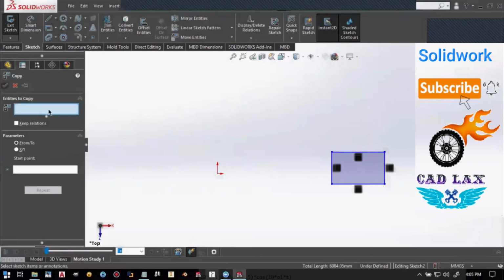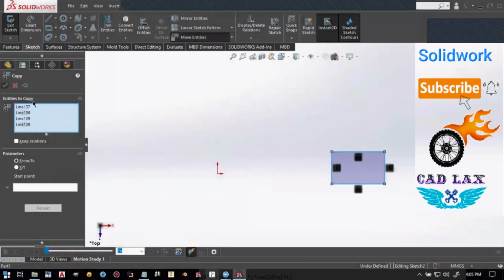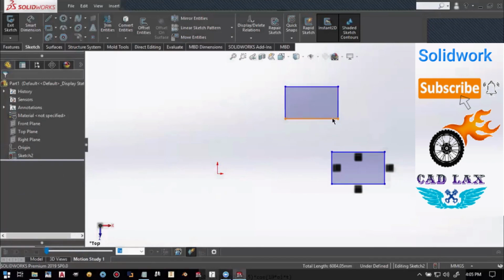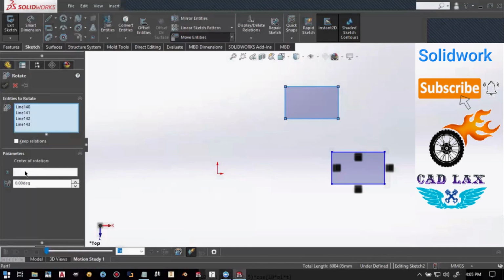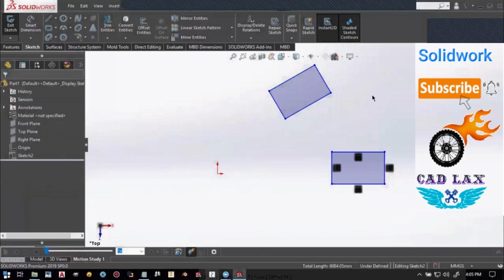Again, the same method is there. You can select the entities to copy. You can take the point and copies will be created whenever you click. Again, rotate entities. If you want to rotate this, select a base point and the rotation angle setting. So it will be rotated along the angle. Next one is scale entities.